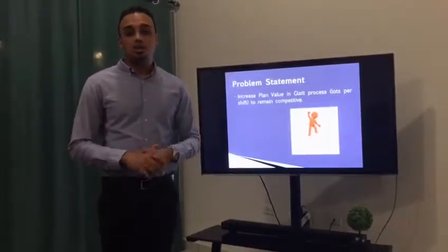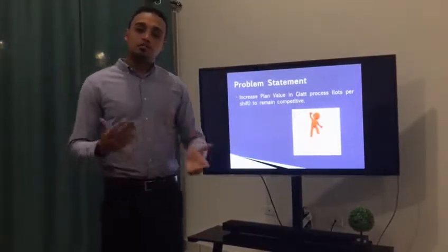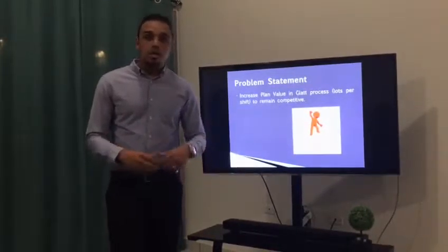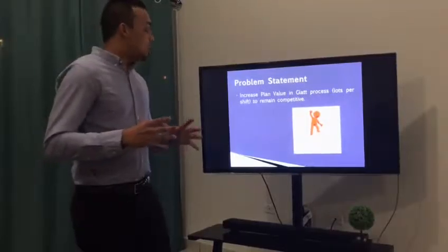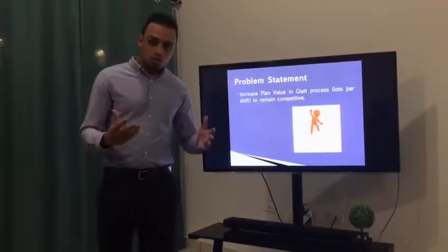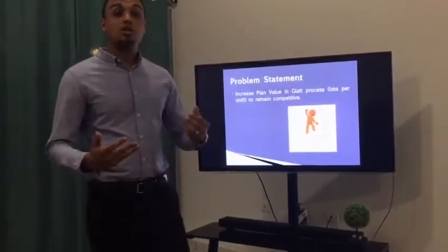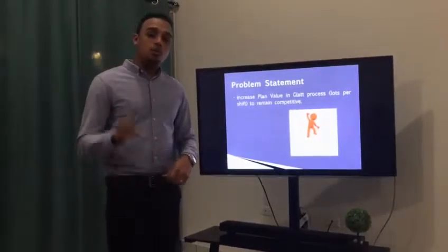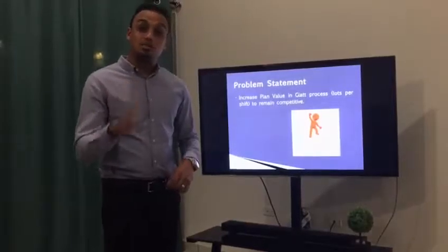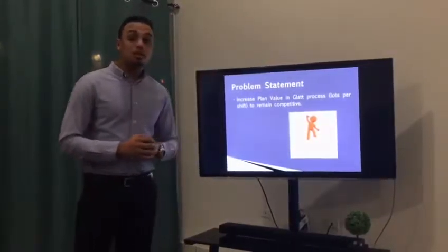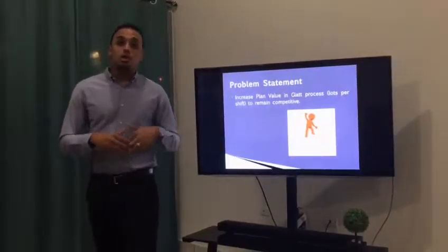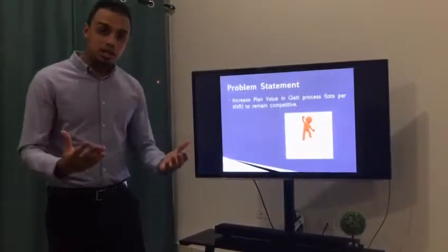Currently, the granulation process is our most critical process. It takes roughly around 2 hours and 40 minutes, and it combines all of the ingredients and creates granules. This is done through suction air, air volume, specific temperature, and with agglutinating solution at a constant spray rate. So currently, our glass process is our bottleneck in our granulation facility.